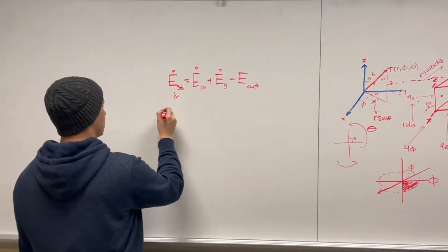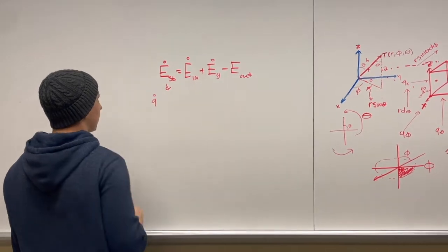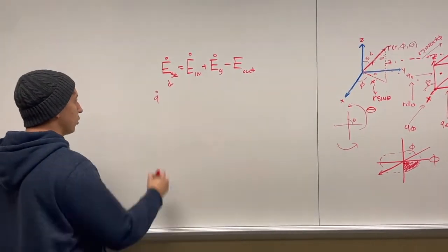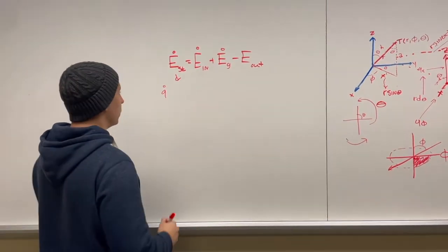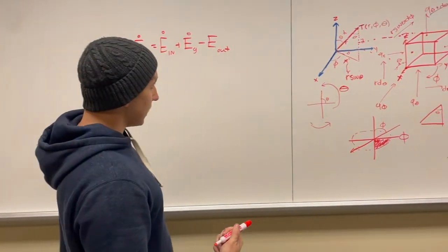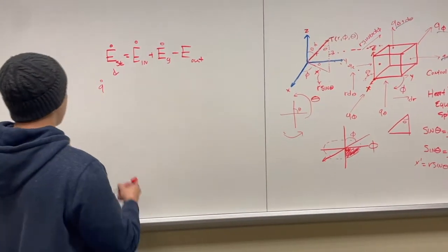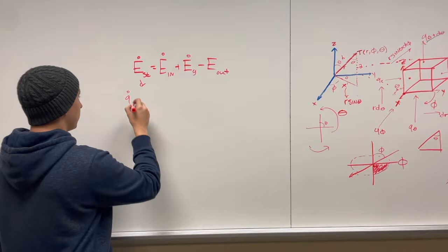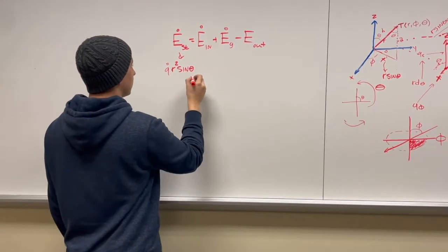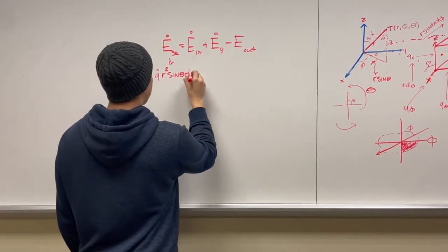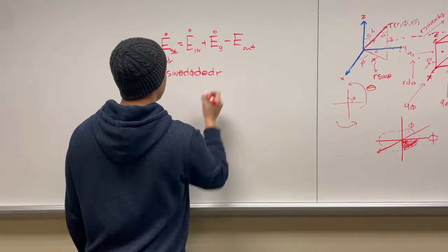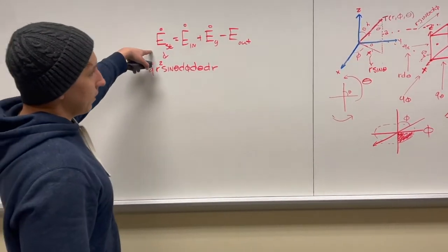We're going to have the same heat generation term, which was defined in watts per meter cubed, times our differential volume. And the differential volume, which I'm going to show you soon, is r squared sine theta d phi d theta dr.